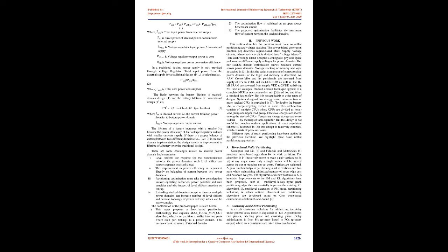The contribution of the proposed paper is stated below. 1. This paper proposes a flow-based partitioning methodology that exploits the max_flow_min_cut algorithm, which can partition a netlist into two parts where each part belongs to a power domain. This becomes the basic structure of stack domain. 2. The optimization flow is validated on an open source benchmark circuit. 3. The proposed optimization facilitates the maximum flow of current between the stack domains.